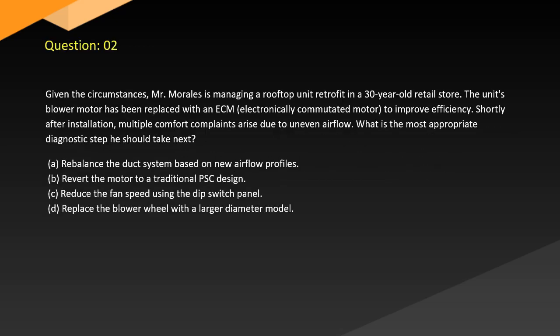Question 2. Given the circumstances, Mr. Morales is managing a rooftop unit retrofit in a 30-year-old retail store. The unit's blower motor has been replaced with an ECM, electronically commutated motor, to improve efficiency. Shortly after installation, multiple comfort complaints arise due to uneven airflow. What is the most appropriate diagnostic step he should take next? A. Rebalance the duct system based on new airflow profiles. B. Revert the motor to a traditional PSC design. C. Reduce the fan speed using the dip switch panel. D. Replace the blower wheel with a larger diameter model.